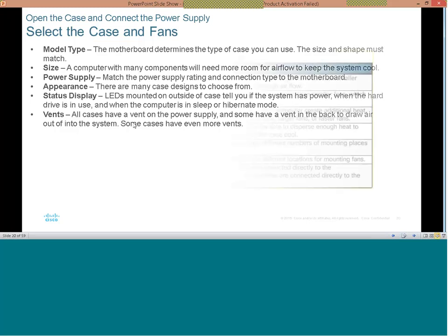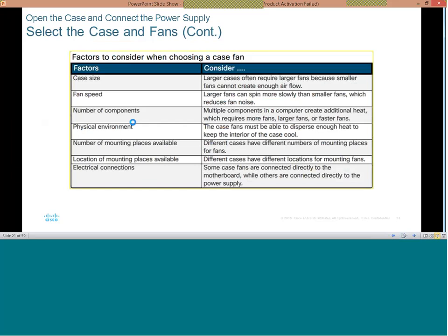So they must know this, and you also let them know that in the course of using their laptops at home, they shouldn't use them on a surface like foam or thereabout, because all those vents will be closed, and before you know it, the system will overheat. And that alone can lead to high component failure rates, because most of the components inside the computer motherboard have a particular mean temperature they operate with.